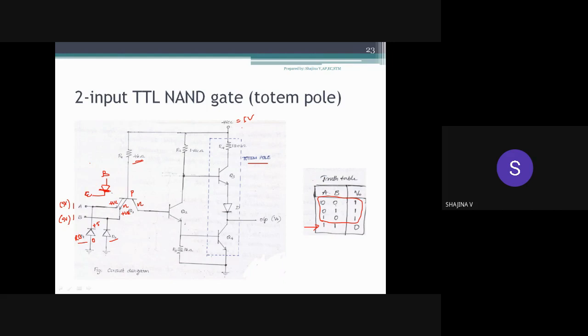NPN transistor, this is N, this is P. Just think of this one junction, the input junction only, like a diode connection. Okay, so to the emitter terminal, that is to the negative part, we are applying a high value, and to the positive part it will be less. So high value here and low value here, that is to the negative part high value, to the positive part low value. So what will be the biasing condition of this base emitter junction?